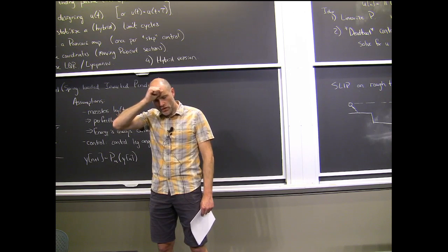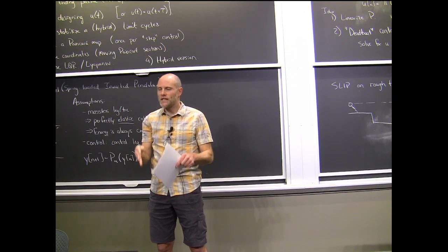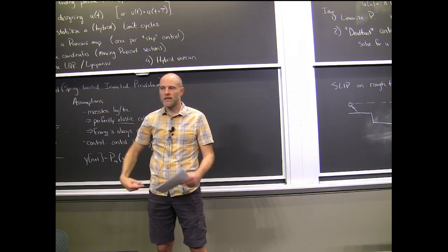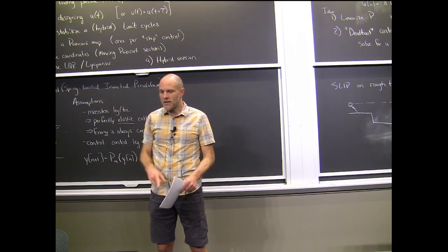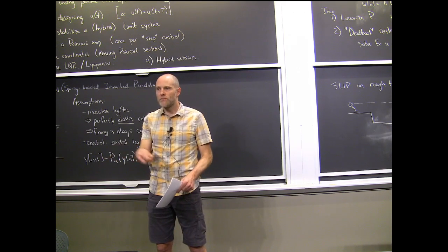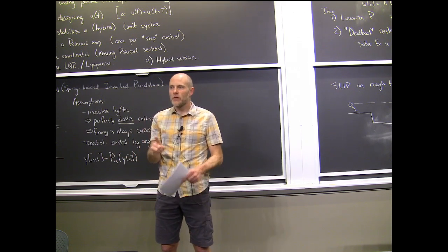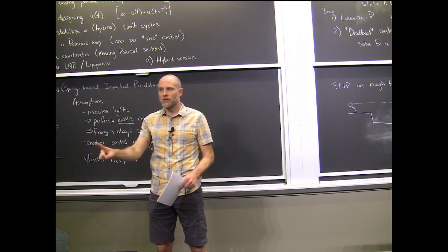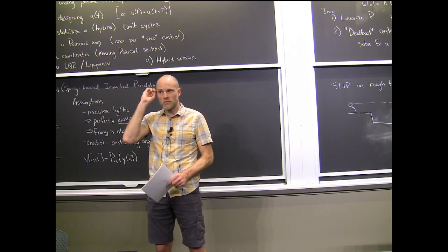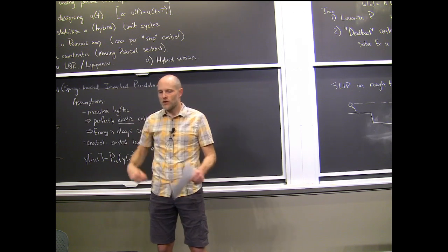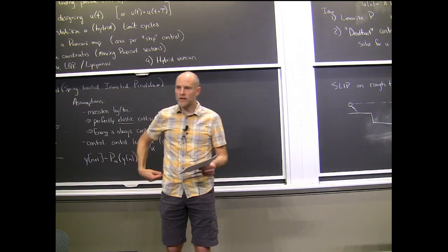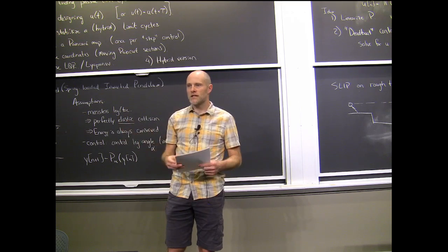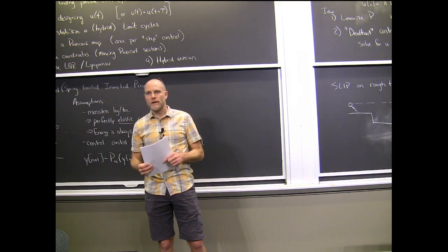I think when people asked what's the minimal thing we needed to add to a passive dynamic walker to make it more stable, this is partly where the questions came up. You might think I'd add a little bit of hip torque, for instance, right? But actually the ability to place your foot is more important if I were to pick one actuator to add. For stability, I'd want to be able to choose my foot placement. That's more powerful in most of these regimes. And you don't have to do it quickly to use that as an effective stabilization mechanism. Yeah, I think you're right that super fast foot placement is beyond passive dynamics.